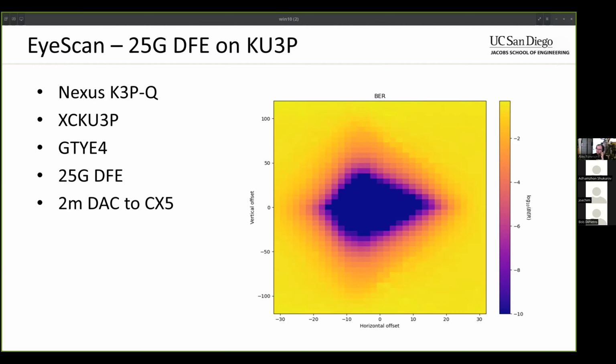My understanding about DFE is that it's necessary when you have a pretty high loss. Yes, I think it's more for, like with a DAC, they have nice twinax going through there. But when you're going through backplane copper traces, that could be a bit lower signal quality, and you'll get more high frequency loss in that case. So it's probably more like when LPM can't open the eye, DFE might be able to. But if LPM can open the eye, then maybe DFE doesn't really help. So I'm not sure about that.